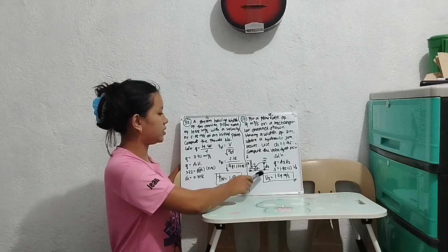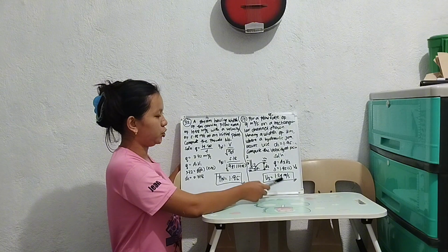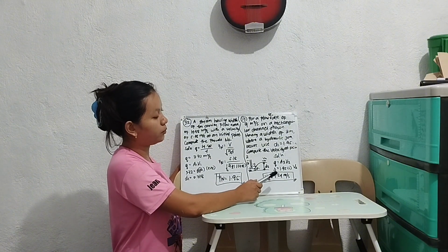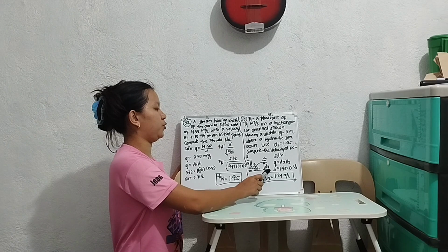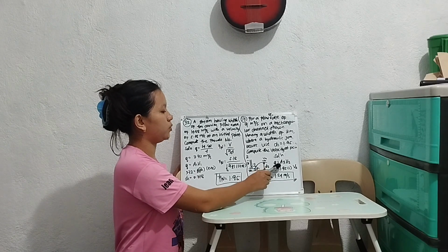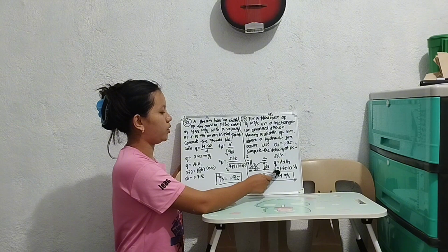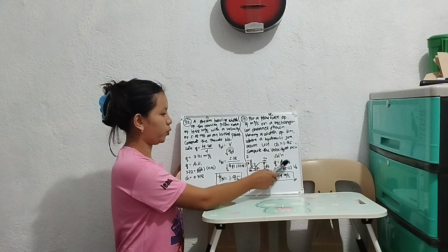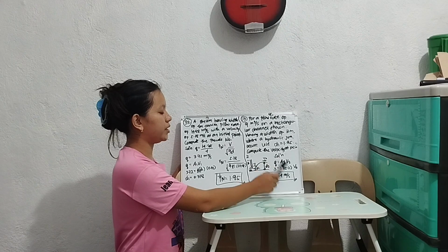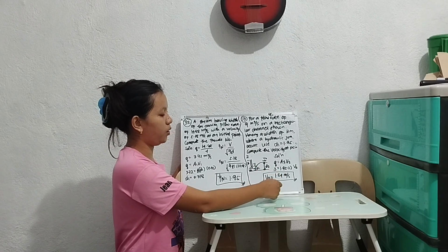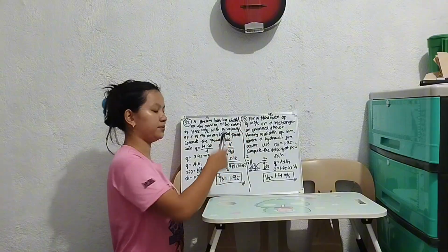This is 3 meters, then the d1, and then the d2, then we have v1 and v2. So our solution, or the formula for this problem, is Q equals A2V2. We have Q, which is 3, equals A2, which is 1.95, times V2. So to answer that, we came up with the answer of V2, which equals 1.54 meters per second.